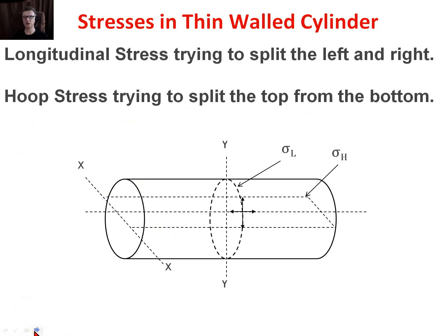So the pressure vessel I'm going to look at is a cylindrical pressure vessel, and I imagine that there's 2 ways I can try to split this pressure vessel. I could either create a split down the side here, or down this side, or maybe at the same time. So some sort of cracking going down the side. I want to avoid the word longitudinal because that is called the hoop stress. The other way that I could crack it is around the circumference here, like this. So we're going to pull it apart.